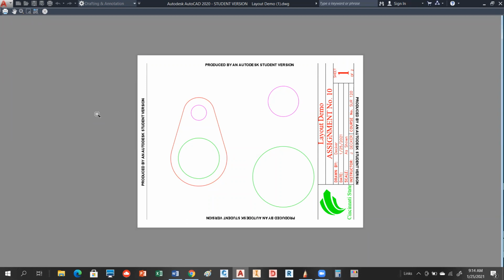Well, there is a way to get rid of that, by the way. What I have to do is save this drawing as a PDF or as a DXF, and then I have this little extension called Drawing TrueView, and you can open it up in TrueView and it'll get rid of this. So you can print from TrueView. If anybody has this showing up on their drawing, I'll show you Wednesday how to get rid of it.